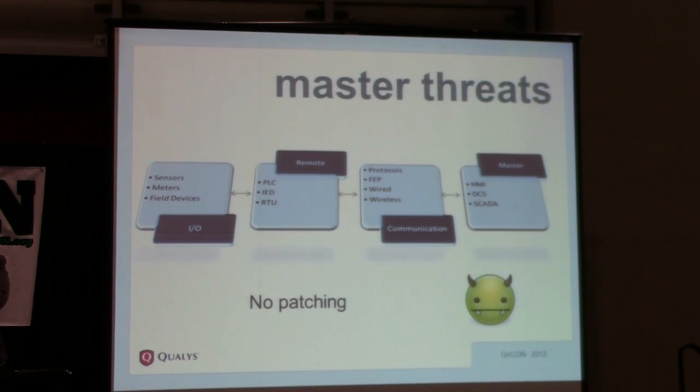This is a pretty interesting subject as far as it comes for Scada system, which is basically no patching. A lot of Scada systems that we saw, none of them were patched, unlike your IT systems which are on Windows and whatnot. None of them were patched. Any guess on why that's happening? Are all Scada engineers lazy or something, or what's the reasoning behind it? They don't want to break the system. So no, Scada engineers are not lazy.